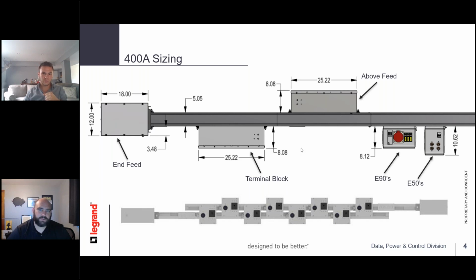The two places that I really see the terminal block being used in the data center world are, similar to what you were mentioning, trying to split the center of a run. If it's a customer that has cable tray, some lighting, things above where the busway is, they'll run that terminal block right in the middle. The second would be these low ceiling height applications.